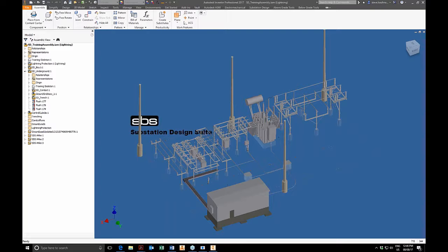How does SDS play with structural designs? Not sure about that one. If a change is made to the sketch, will the ground grid design automatically update? Okay, all right. So those are two different questions from Richard. So Richard, it doesn't play with structural designs; it's totally independent of SDS and how you use Autodesk Inventor to make your structural design. If you make your structural design out of Frame Generator, you change your sketch and the structural design will change automatically. Many people will template their models and store them in Vault or other data management like Adept, and they will place that stuff in there and use it as a library to pull the parts out.